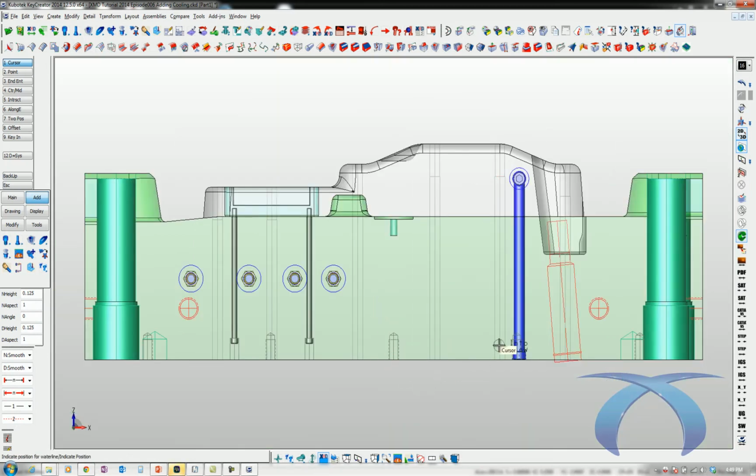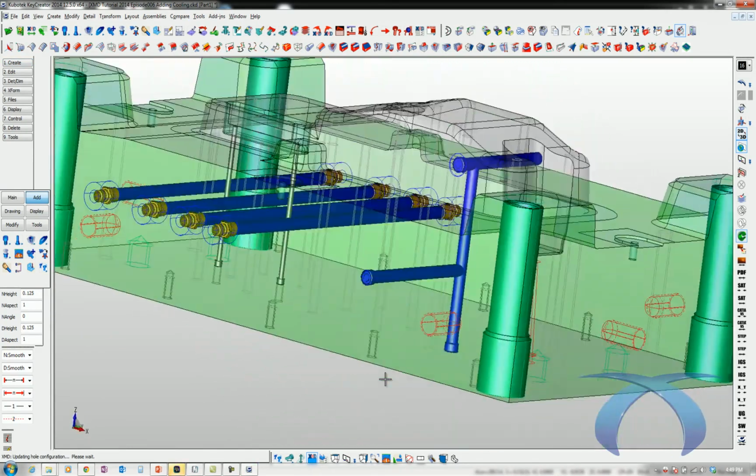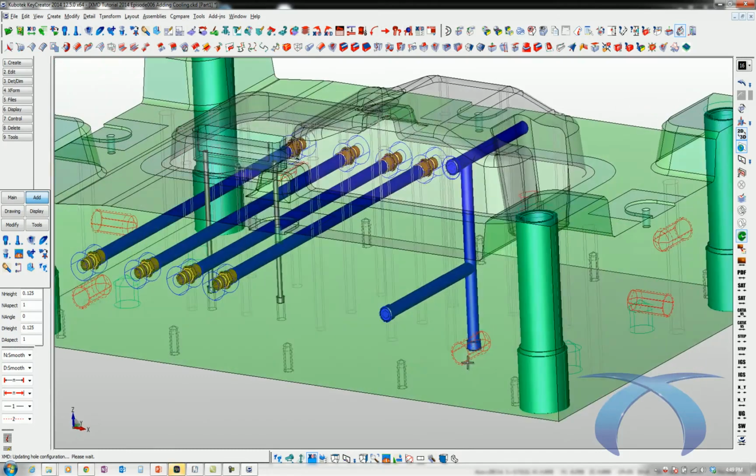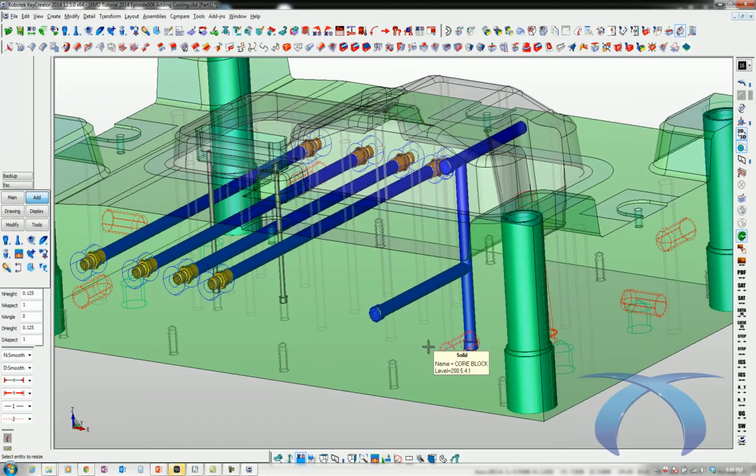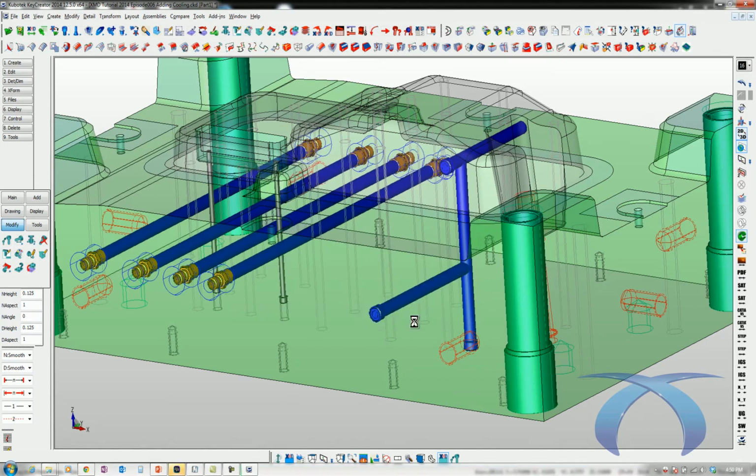And then if I go to here, and let's place a line up here. Okay. So now when I go here, you can see I got these 3 lines I just placed, and they're all trimmed automatically. It understands where to trim those lines to and where to stop. So now what I can do is use my modify size button to click on this pipe tab, and I can actually turn off the pipe plug, switch to a connector, and add a counterpart.